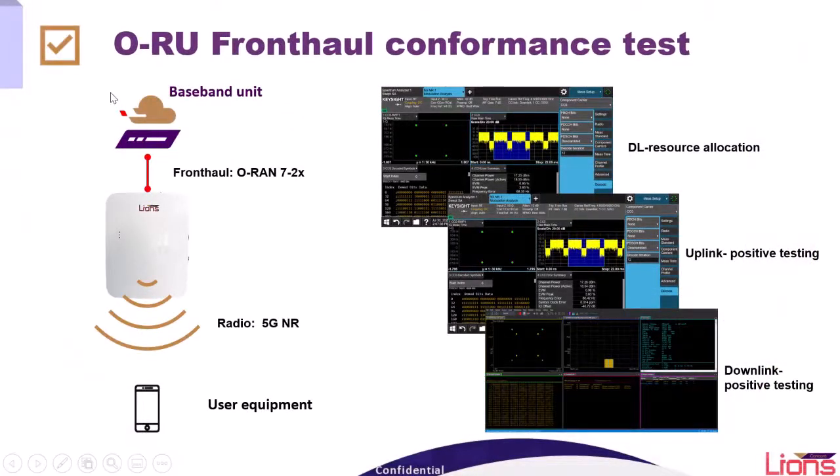The first aspect is about the ORU conformance test, which covers the fronthaul side to ODU and the radio side to UE. On the upstream side, the test verifies that RANathon ORU can work with an ORAN 7.2x split compliant BBU. On the downstream side, 3GPP compatible 5G UE can connect to RANathon ORU with satisfied and reliable performance. Radio testing including base, uplink, and downlink cases are conducted and reported. It guarantees the interoperability of RAN with UE as well.